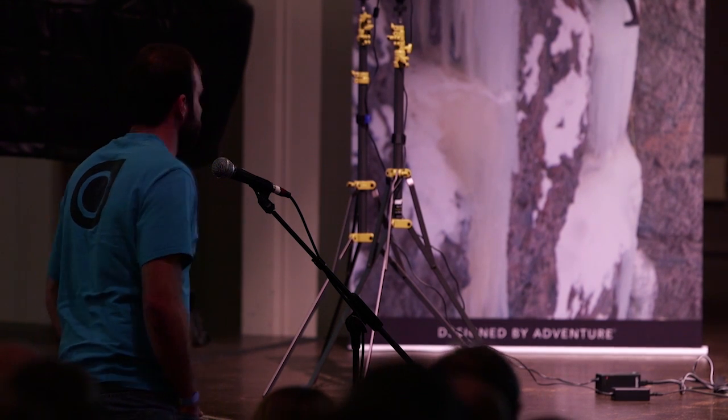Yeah, good question. I skipped over a lot of the nuts and bolts there. At the settings that we use, it takes us about 25 minutes to do a 180 scan, which isn't all that long, I suppose. The resolution can be varied quite a lot. It's an angular resolution. It comes out to about 500 meter range. We're getting about 10 centimeter spacing. So we're getting a snow depth every 10 centimeters for much of that terrain.